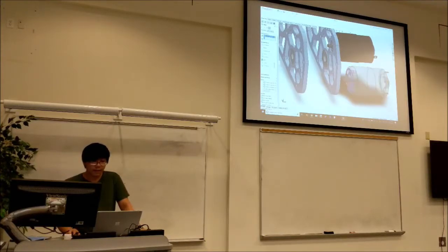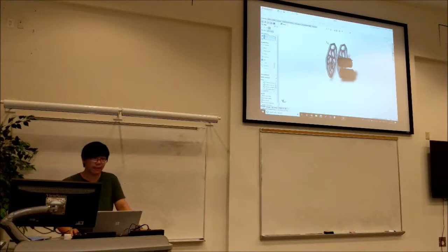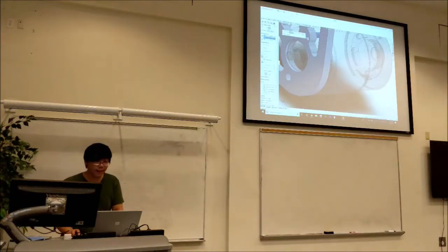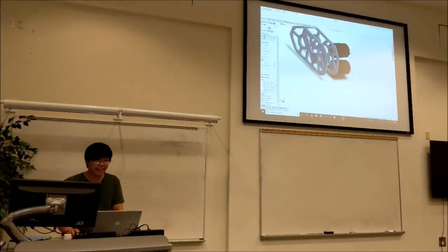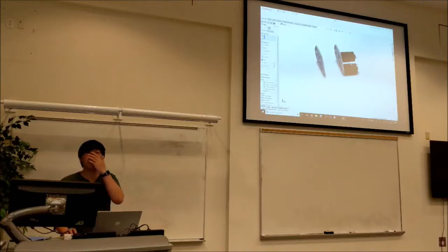So we normally just do prototyping, because when you do quarter-inch aluminum plate in FRC, for the most part, unless you're on an edge case, it's going to hold up fine as long as your pocketing is reasonable. So we don't do CAD-based analysis, but if you have the resources in terms of number of team members, you could. We're a small team, so we don't do that.